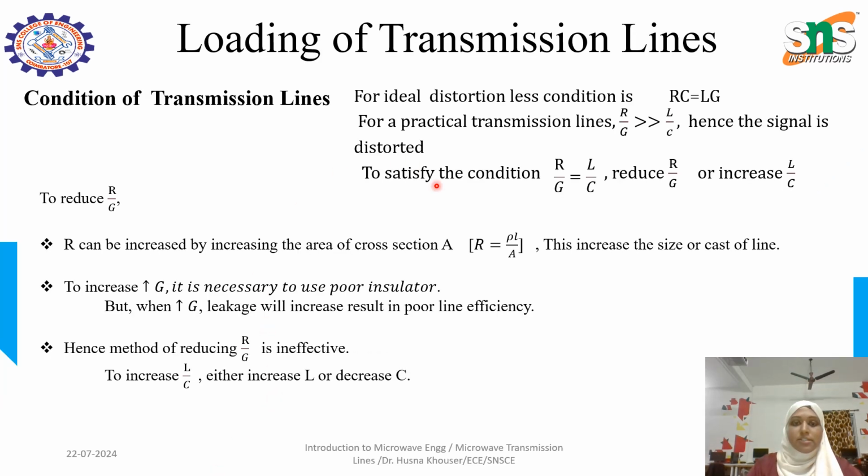In the last lecture series, we discussed waveform distortions. While discussing waveform distortion, we saw the distortionless lines. For an ideal condition, when we are transmitting a signal, there should not be any distortion. That is, whatever signal is transmitted, the same signal we have to get at the receiving end. That is the ideal distortionless line. For any ideal distortionless line condition, there is the formula RC = LG. This we already discussed in the last lecture series.